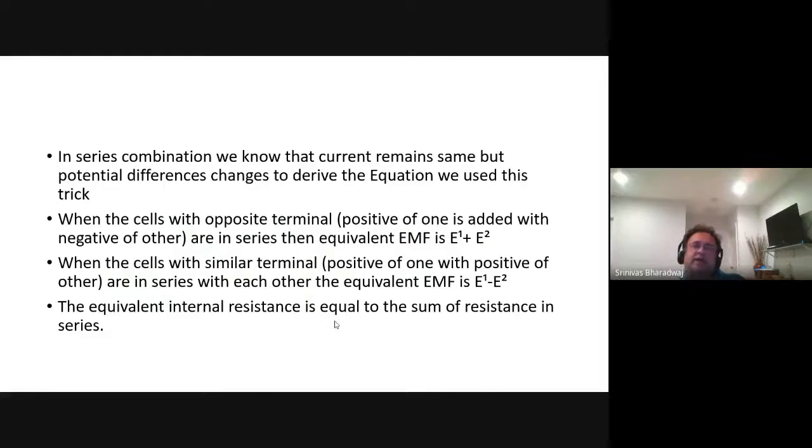Okay, and in any resistance, if let's say the current is going this way, this is a minus. This is a resistance, current is going this way, it's a minus. I times R leads to a potential drop. Okay, so that's how you evaluate. Go one loop around any circuit, you should get 0 because you've come back to where you started. There's a law for it, and I will discuss the law just now. The equivalent internal resistance is equal to the sum of the resistances.